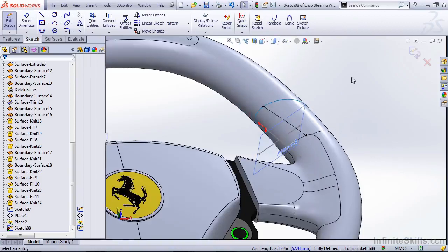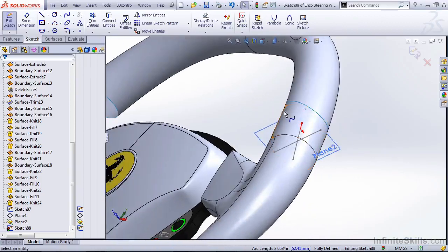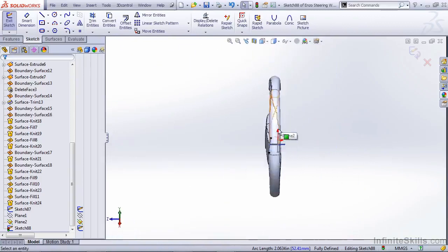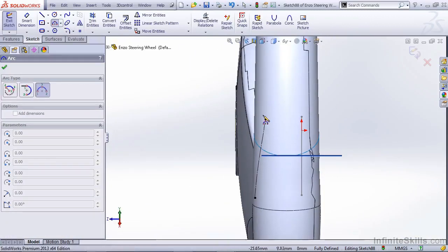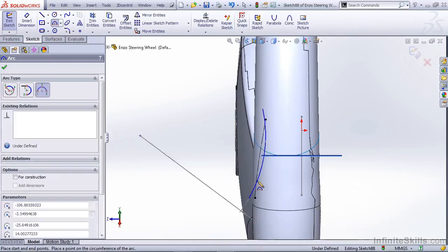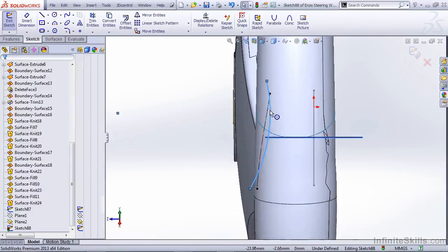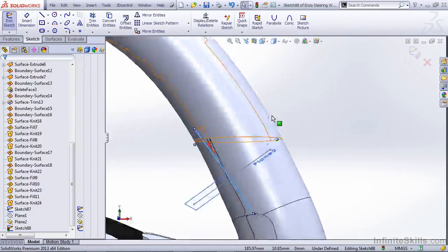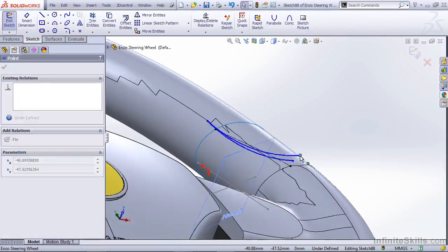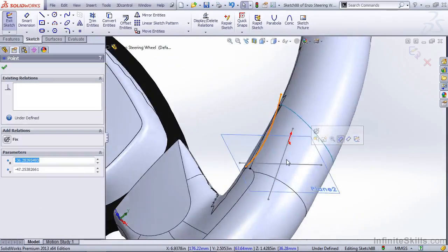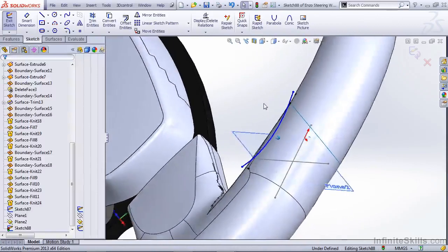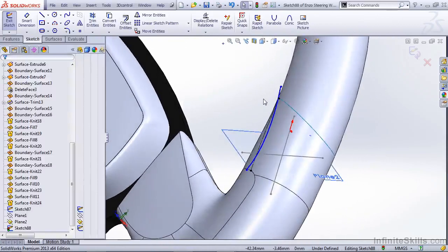And now I want to create some geometry for our thumb section that's going to intersect with that. So if this is our surface, I'm going to create a 3-point arc. I'm going to use a start point, an end point, and just simply give it some curvature and make sure that we're intersecting the surface. So if we rotate this around, you can drag it around a little bit and keep in mind that we don't have any defining geometry for this. So everything is going to be based on look and feel for these surfaces.